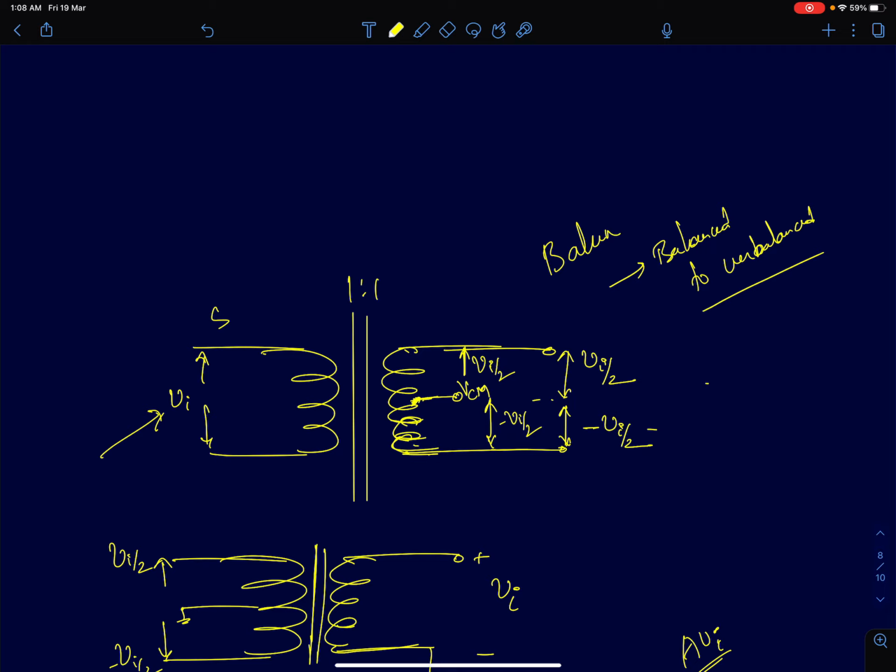So these are terminologies which were borrowed from radio frequency circuits. Balanced generally means differential signals. By then, the idea of generating differential, opposing phase signals was well developed, because there was already a rich literature in AC power transmission. So from that, we could directly use a center tap transformer.